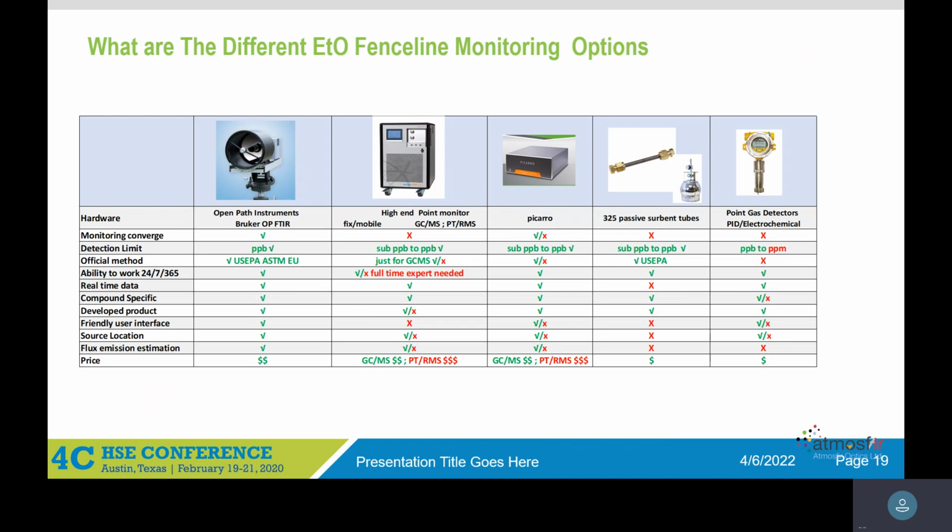And then we go to the open path instrument. In the case that we are talking about, the most suitable will be an FTIR. We can go to ppb level. It's a proven US EPA method. We will not go below 1 ppb, but if the threshold will be around 2.4, we are well below that. We can measure it, and we can give real-time data with certainty.